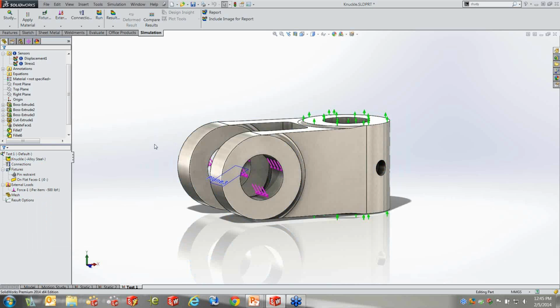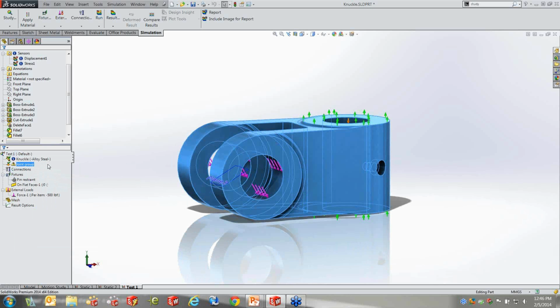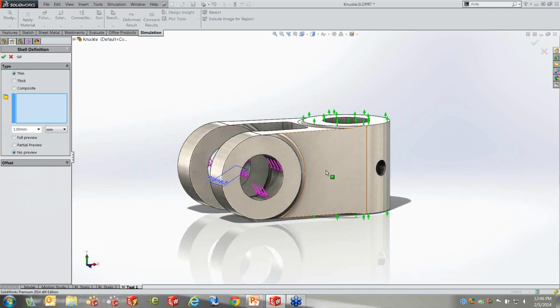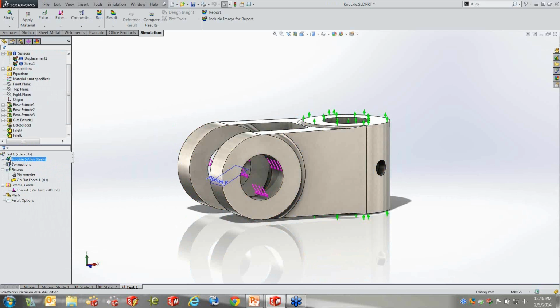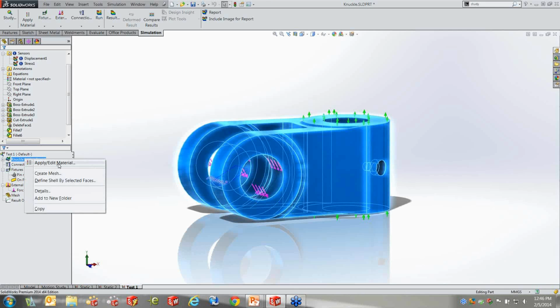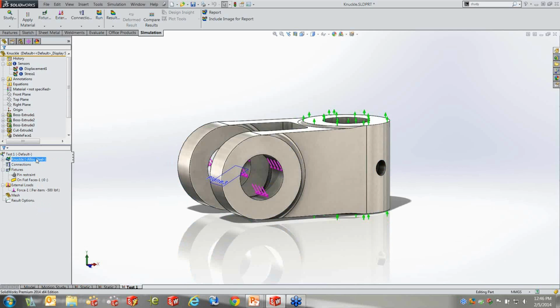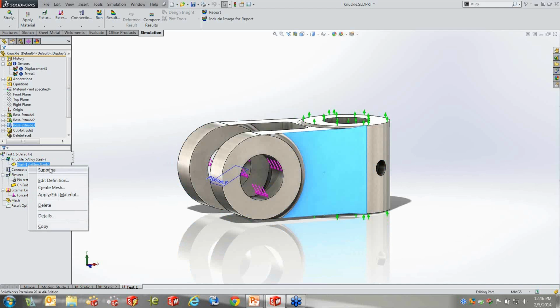So I guess, since we're early in this conversation for simulation, the best thing to think about getting going is to just pay attention to the different icons that you have here. And I'm just going to treat this as a beam just so you can see. So if I treat it as a beam, I get a different icon. If I go back to treat it as solid. If I treat it as a shell, I can pick a surface here, and I just want to show you the symbol for a shell. Okay, the symbols actually give you some indication as to what we're dealing with here.